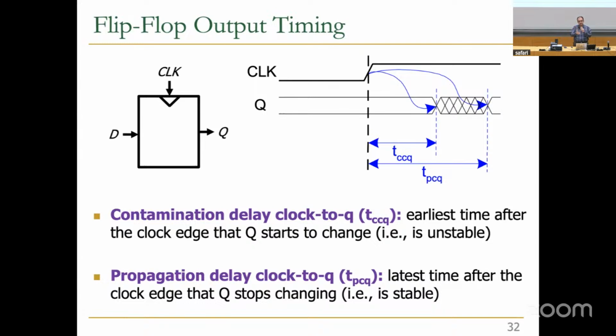And when you sample during that time, you can see that it's not logic 1. Logic 1 might be like 5 volts, for example. So if you sample, you're going to see that at this moment my output is 1 volt, which is not 0 and not logical 1 either. Then you wait a bit more and see my output is 3 volts, then 4 volts, and in the end it's going to be 5 volts. So you always want a stable situation where your output is 0 volts, which is logic 0, or high voltage, which is logic 1. And between that is your unstable situation that you want to avoid, essentially.